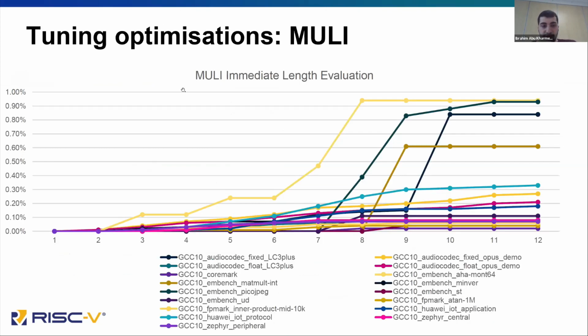So the third point is the encoding space, and we make sure that our instructions don't actually waste encoding space. What we can do is tune the encoding space, run the fitting criteria for our optimization, and then run the replacement again and again until we see the sweet spot for the maximum code savings while wasting the least amount of encoding space, because encoding space is really valuable.